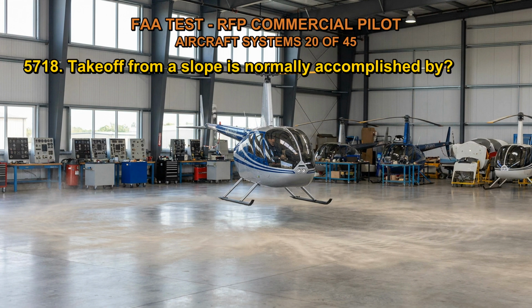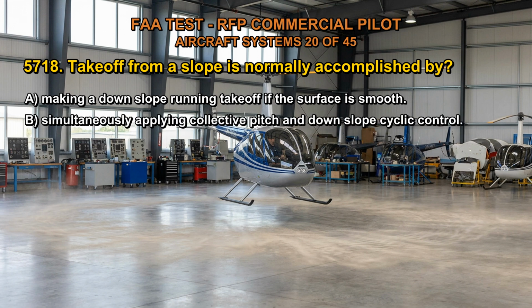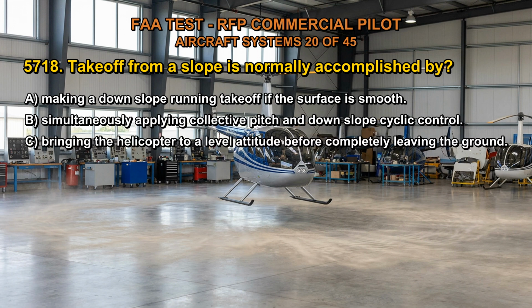5718. Takeoff from a slope is normally accomplished by: A. Making a downslope running takeoff if the surface is smooth. B. Simultaneously applying collective pitch and downslope cyclic control. C. Bringing the helicopter to a level attitude before completely leaving the ground.